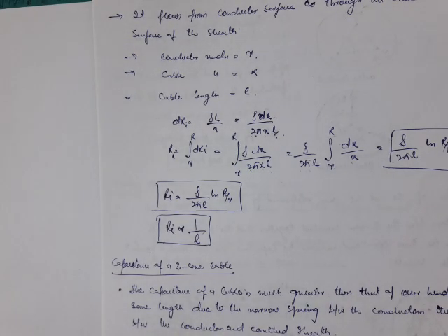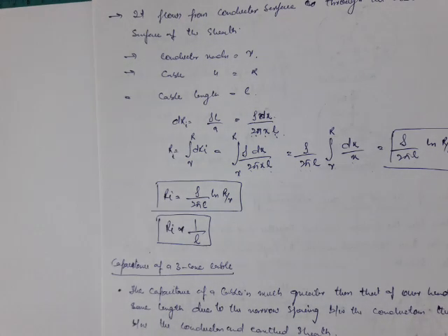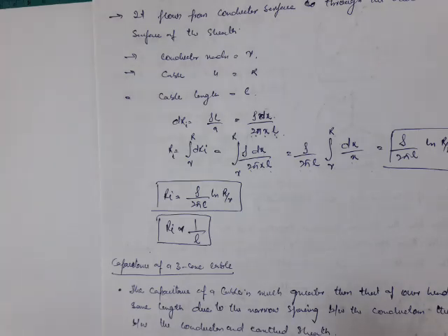In the previous sections we have seen that the insulation resistance is usually directly proportional to length, because that length is the length along which the current flows, but this length is not that length. This length is perpendicular to the direction in which the current flows. That is why in this case the resistance is inversely proportional to the length of the conductor.